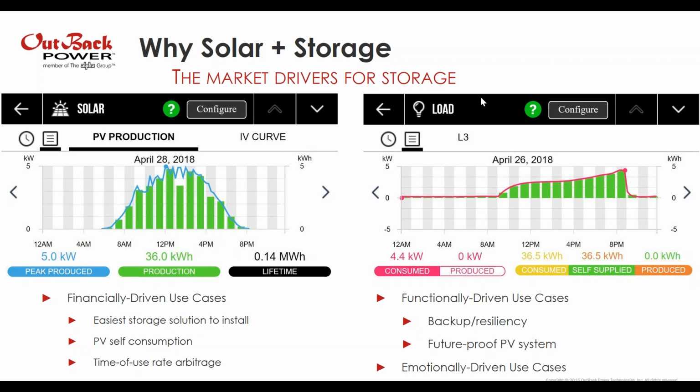And on the right, you see that the loads reach their peak late in the afternoon after the sun started to go down. That's peaking around 8, 9 p.m. at night. So what's SkyBox doing in this particular case? Well, it is serving those loads early in the morning and charging batteries simultaneously. And then in the afternoon, it's discharging the battery and using that to supplement the PV production to serve those loads and have 100% self-consumption.